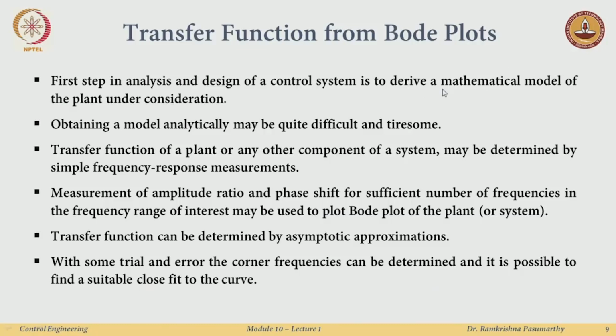The mathematical model which we used so far very extensively was the transfer function. Sometimes it may not be possible analytically, or I may not even have any information of what the physical components sitting in the system are. Therefore, I employ a technique where I can just plot the frequency response of the system and see if I could get to the transfer function.